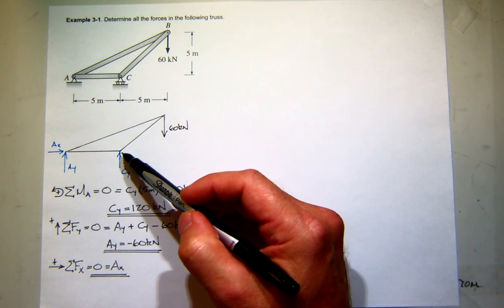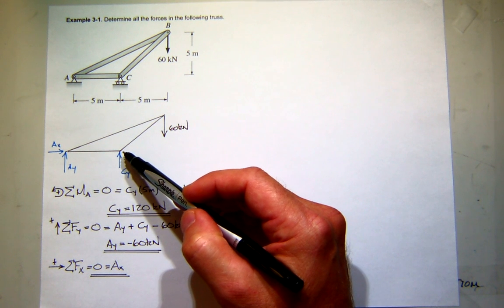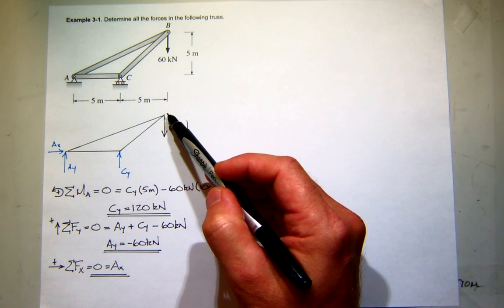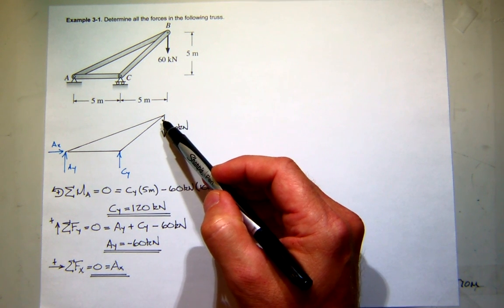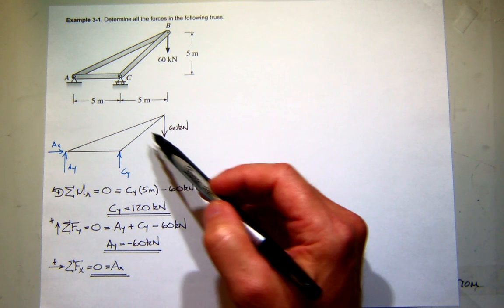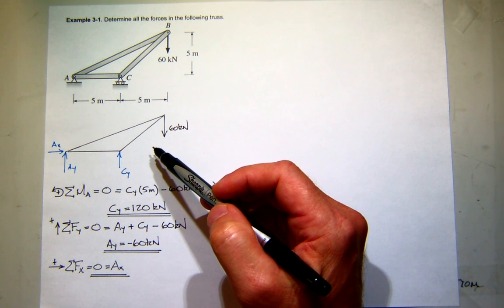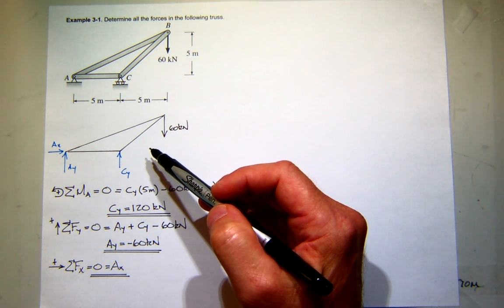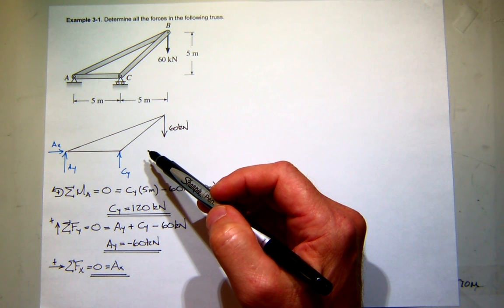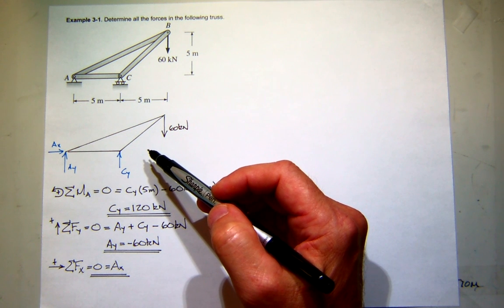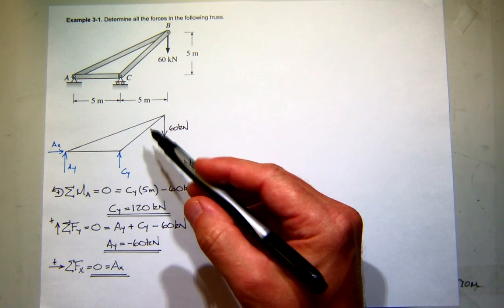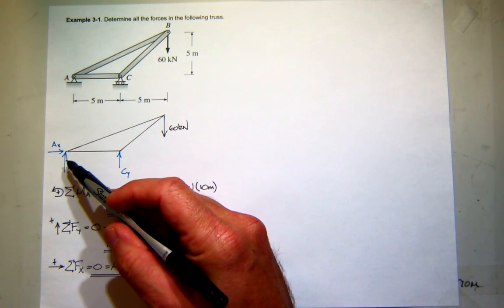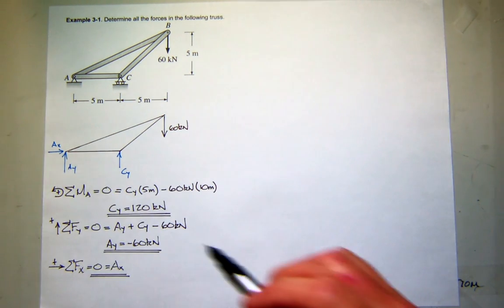What about at C? Same strategy. What about at B? Unless you rotate your axis, both of those bar forces will have X components and Y components. Unless you want to solve 2 equations and 2 unknowns, that's not a good place to start. So there's a little bit of strategy here. And I'll just, because A comes before C in the alphabet, I'll start with A.